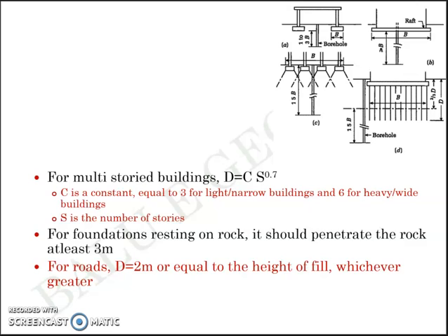For roads, D is equal to 2 meter or equal to the height of the fill, whichever is greater. For gravity dams, depth is equal to twice the dam height, etc., etc. So these are the standard guidelines that we follow.